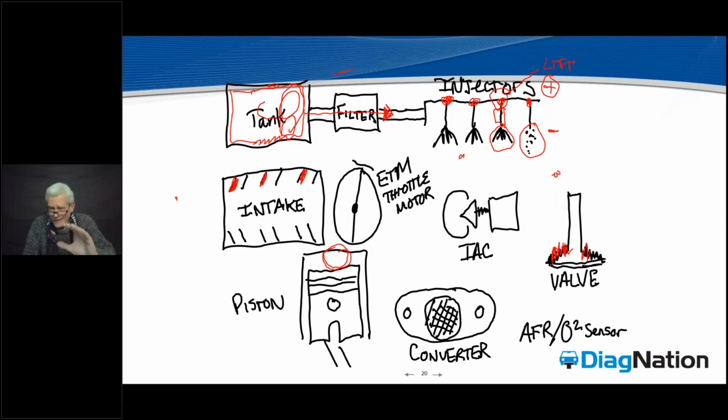The signal that you can take to the bank with any gas direct injection car that it's starting to get into trouble with this right here is a shake at idle. Okay, with your foot on the brake, car in drive, assuming it's not a Honda Accord with bad fluidic motor mounts, that idle shake, it's purring at idle. And if you just crack the throttle open, I'm not talking rev it against the gas pedal, right? Not brake torquing it. But if you have that idle shake and you just crack the throttle and it smooths right out, you better pay attention to this data, guys, because this is your problem, okay?